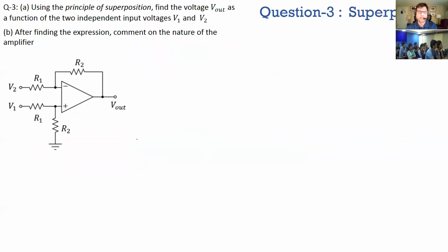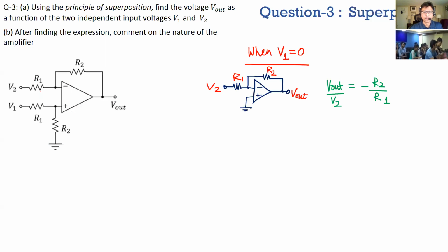All right, so in an electrical example, this is again the same problem I gave during the quiz. We have this op-amp circuit, and I asked to find the output for independent voltage sources V2 and V1 using superposition, right? Now, in superposition, like we said, we make one input 0, apply the other input, find the output response, do the other side, and add them up together.